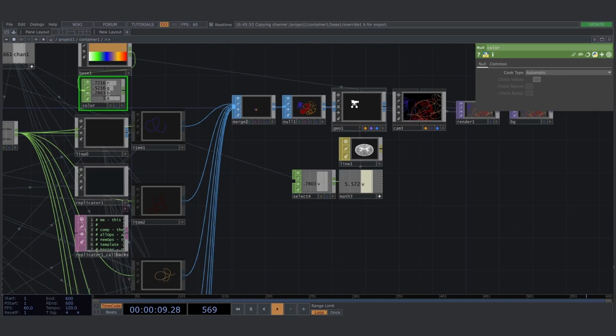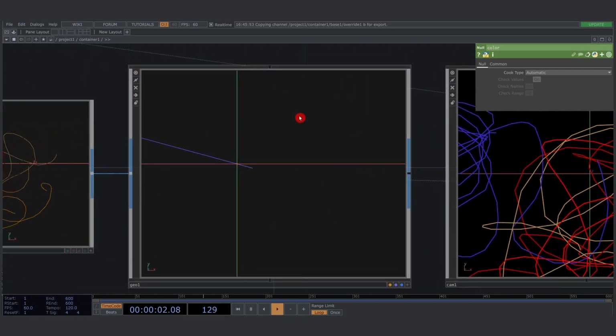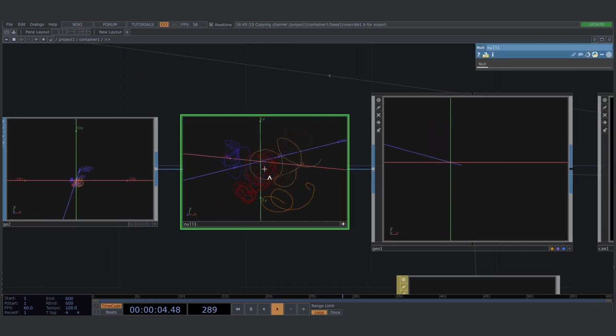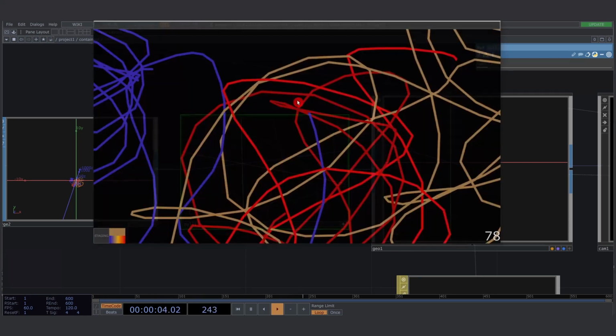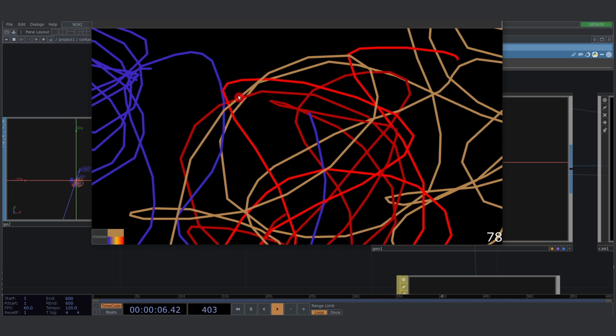Now I should stay inside of this one. And if we go to the geometry, or maybe already this one, you see that they're z-fighting, it's called. It's when multiple geometries are actually laying on the same z-axis position, being 0 on the z-axis, then the GPU or the project doesn't know which one to draw first, which one is laying on top, which one is laying on bottom. So it's doubting, and therefore you also get this flickering between the different colors.